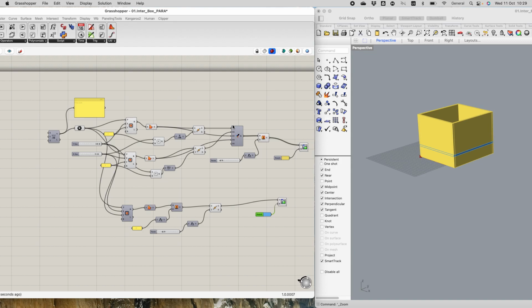It's just inevitable once you get the grasp of it, because when I go now to Rhino, I always switch from Rhino to Grasshopper, but I would say 90% of the work is done in Grasshopper. And then I just do the end bit when I need to figure out the mesh at the very end. If I want to, for example, send something to a 3D printer, or send something to a factory and they want to have a DXF, it's the end part that is then done in Rhino. The entire design work, I do everything in Grasshopper.